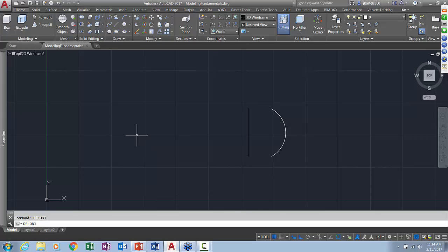So first thing that I'm going to do, when I launch AutoCAD, is make sure that I'm viewing the 3D modeling tools. One way to do that, I'll just come down to the lower right corner here, and I'll ensure that I'm using the 3D modeling workspace. You can see there's a couple of them here. There's the basics that'll give you just the simplified version of the tools, but I'm going to choose 3D modeling. It gives me all the functionality.